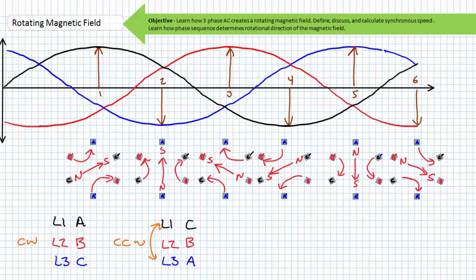Again, note that the poles on either side of the pair at maximum intensity are likewise contributing to this counterclockwise rotation effect. Any single pole rotor immersed in this stator field would be attracted in succession to the C-C prime pair, the A prime A pair, the B-B prime pair, the C prime C pair, the A-A prime pair, and the B prime B pair, and return to the C-C prime pair, having completed one full revolution counterclockwise.